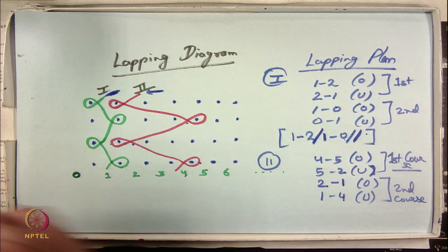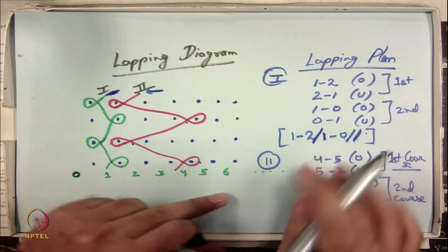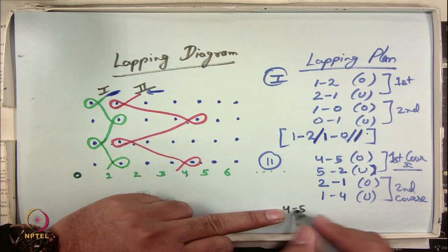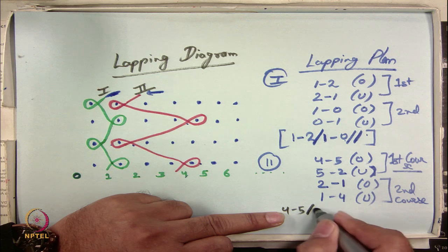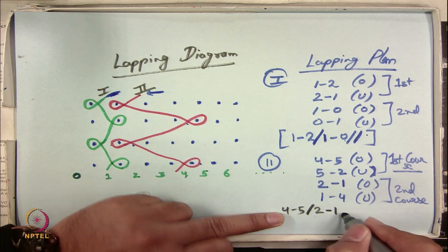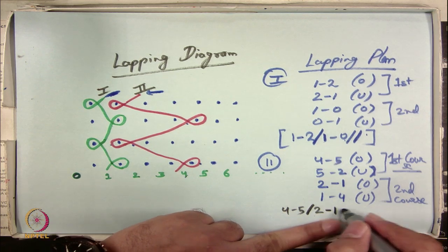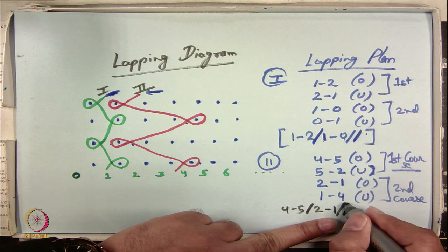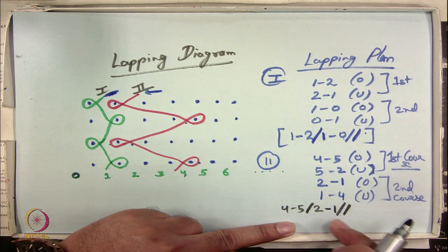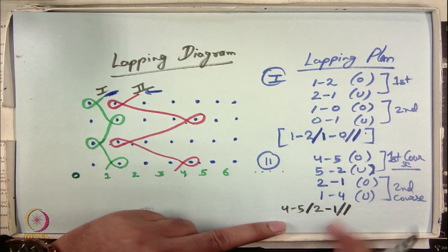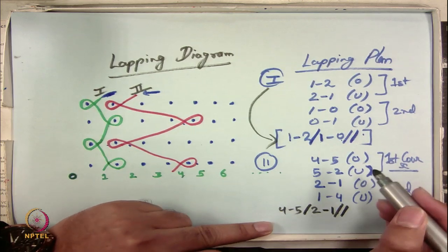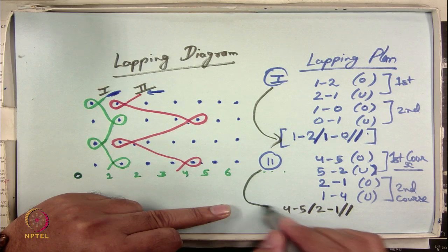Okay. So, if you combine these numbers in a sequence, 4 to 5 denotes an overlap by dash, and by oblique 5 to 2 this is underlap, and then from 2 to 1 again overlap, and after 1, 4 is coming which should be underlap. Since we do not need to repeat the entire same numbers, we just give the stop signs after one overlap symbol. So, 4 5 2 1 and 1 2 1 0. This is for the first guide bar and this is for the second guide bar.